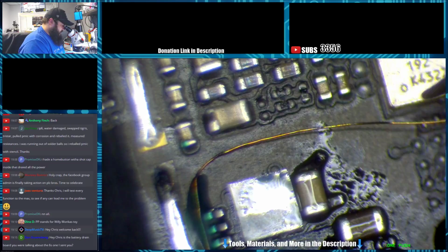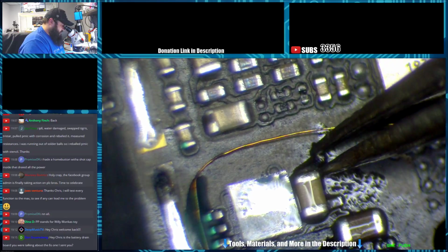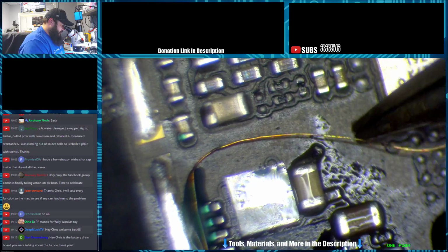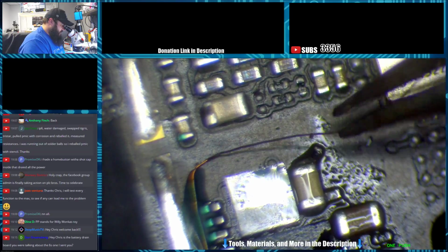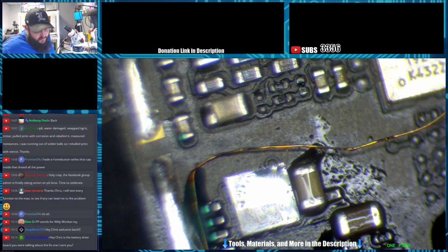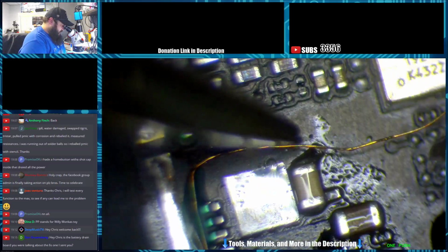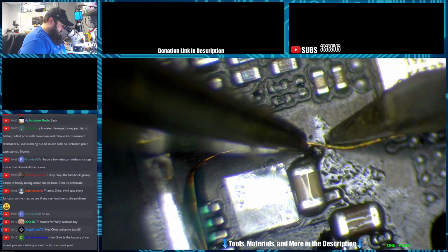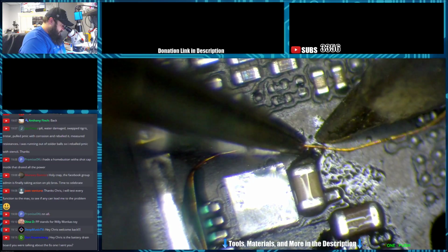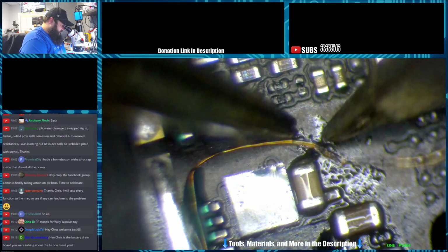Dan, yeah, that's the one that I'm still trying to figure out. I can't seem to find what's causing the short. I've tested it with everything disconnected. The only thing that I could tell is when I did turn off cellular data, the amp draw on my DC power supply would go away. But that doesn't really help me since cellular goes to a lot of stuff.